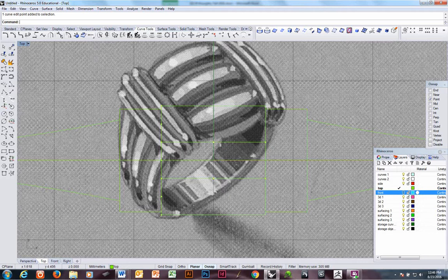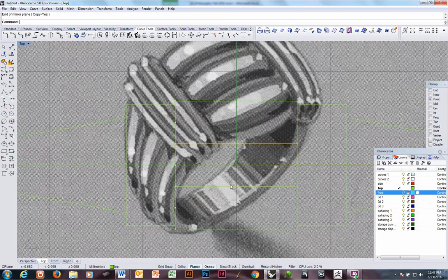Okay, so if I grab this, that curve is going to stay tight through the point, which I want. But I want history and symmetry, so I'm going to record history, mirror. When I hit mirror, guys, I don't say anything, so you're going, what's he doing?